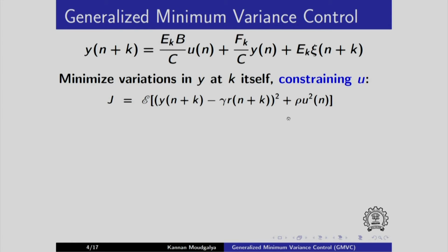So here is the objective function that we will minimize. We will minimize a multiple of U squared using a tuning factor called rho. If the control effort U becomes very large, we will increase rho, the weightage, so that when we minimize this objective function, U will automatically get reduced. We will learn more about it later on also. For now, we will include rho as a tuning parameter that is used to reduce the effect of U.